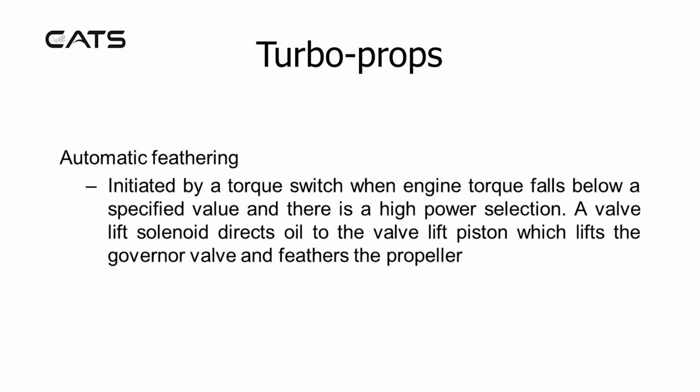Automatic feathering. This is achieved by a torque switch when the engine torque falls below a specified value and there is a high power selection. A valve lift solenoid directs oil to the valve lift position, which lifts the governor valve and feathers the propeller.